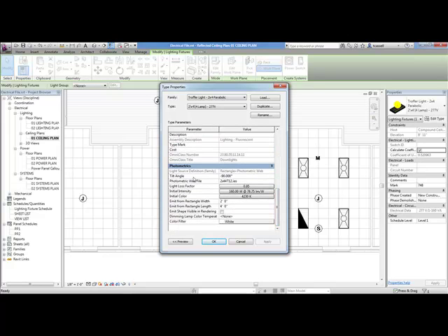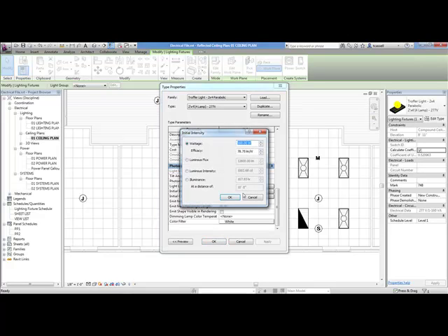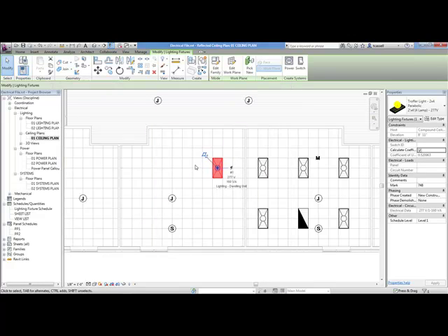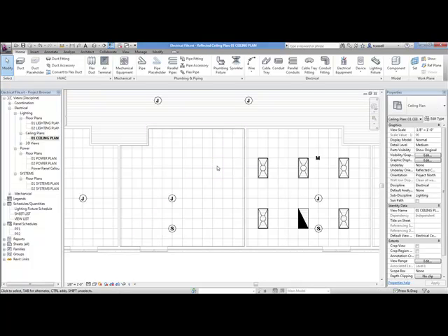So as a lighting designer, this program can be very beneficial to you as well because it can give you average illuminance for a room. We can attach wattages, luminous flux, and illuminance. So different engineering information can be applied to these fixtures. And as they are dropped into the file, the file gains that information and stores it in the database, making it transferable to the circuits, to the panels, to anything else that we need, to the spaces.